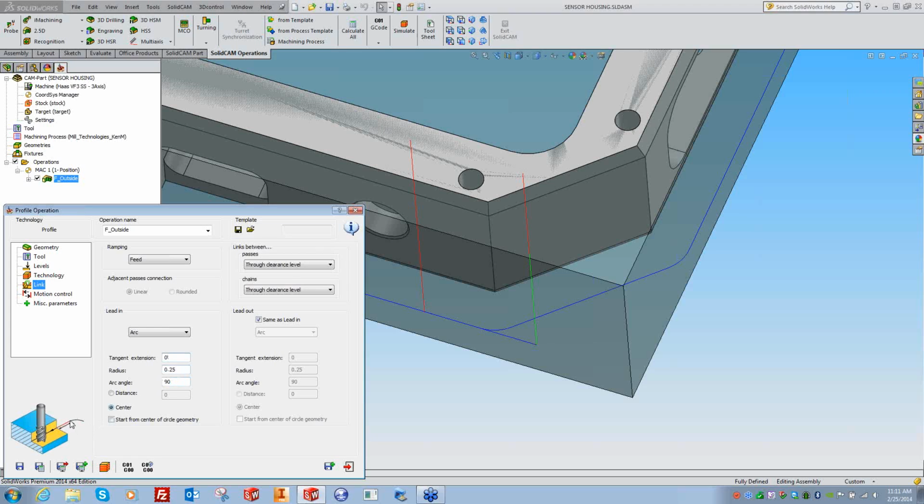So as you click in here, you can see you can add a little line in here. You can define your arc size. You can define how much of that. You can do 45 degrees if you wanted. That'd be fine, or 10 degrees, doesn't matter. And you can turn on a little straight line move. Most machines require a straight line move to turn cutter comp on, that G41, G42.